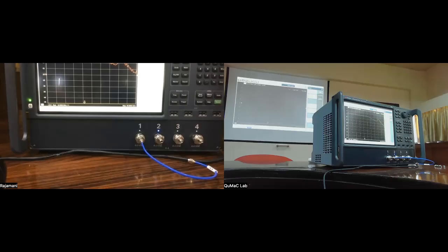So when you are doing measurements of linear systems, which most of the things we'll be looking at are, in fact, all of them are linear systems, you should use the maximum power possible or the recommended power range. Now, sometimes the accuracy of the instrument itself might change with respect to the power range. And this is again because different power levels mean that something inside is changing, and that can affect the signal to noise ratio a little bit.